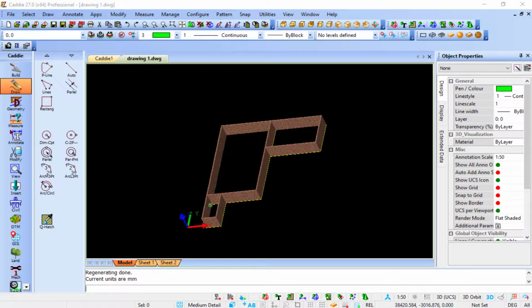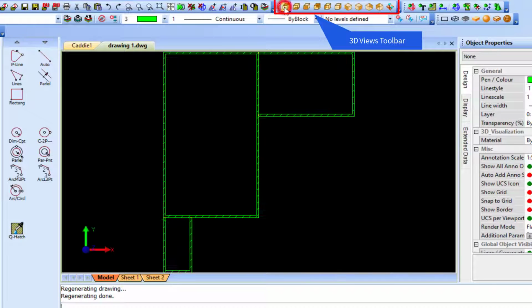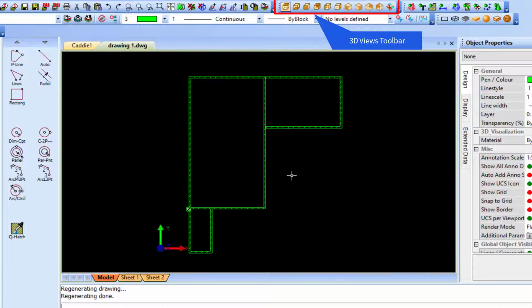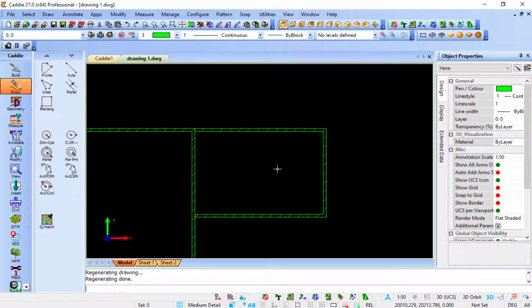So now I'm going to show you how to create your pantry as well as your storeroom and your glass wall office. Now if I go T for top view, you'll see there at the top, my pointer position. If I left click, it also gives me the same command. I like to use the keyboard shortcut T for top view. So now I'm in top view, and let's start off with the pantry over here. I would like to make use of 6,000 to the left and 3,000 up.